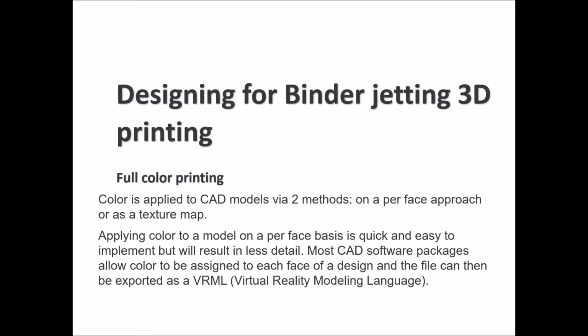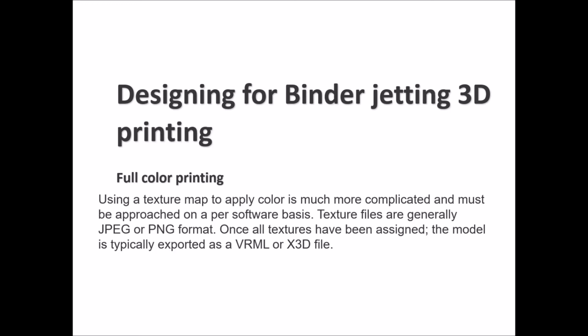For the CAD software packages that allow colors for each face, the file can be exported using the Virtual Reality Modeling Language, which is abbreviated as VRML. If you are using a texture map, then it will be a little bit more complicated and it can be done through outside software in most cases.